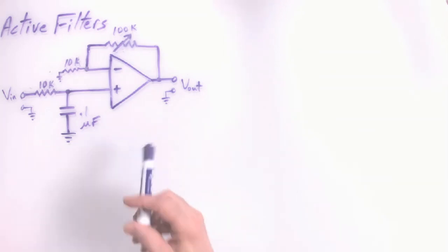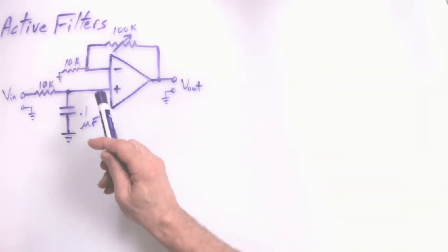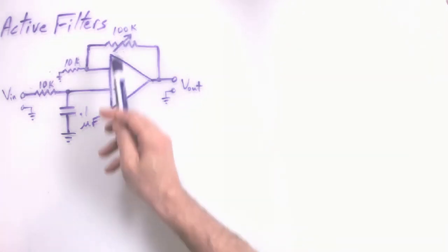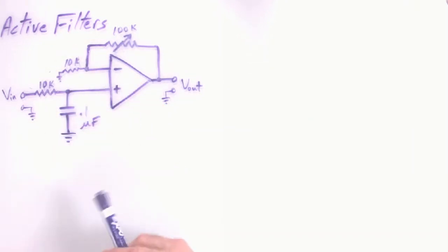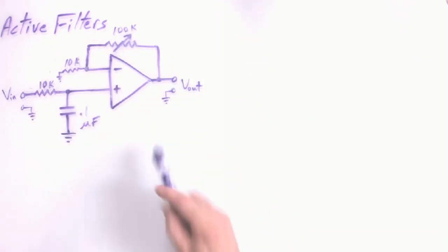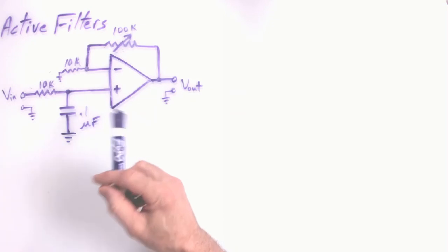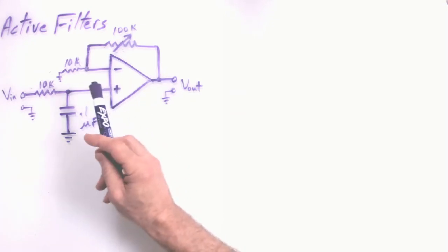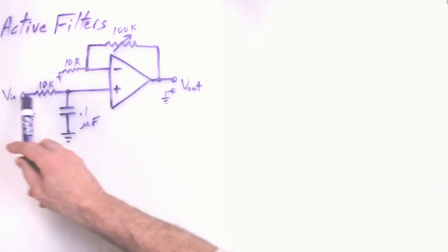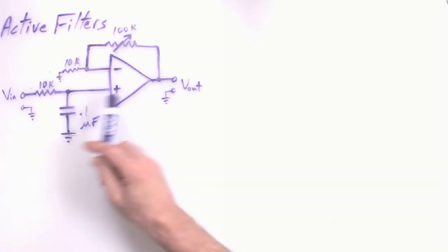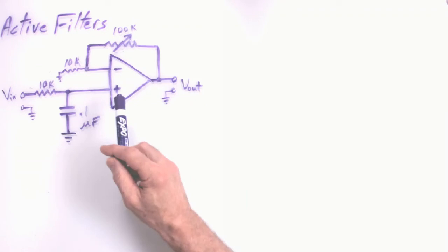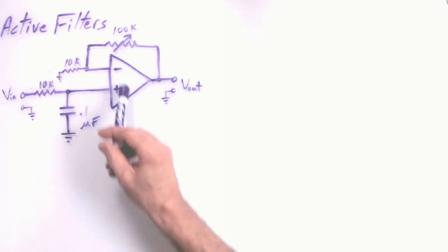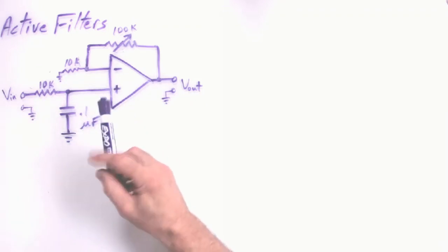And I just caught myself. I think I've been saying that we have a gain of 10 in our example. Has that been bugging you this whole time? So I'm losing points on a test there, right? My input is over here. It's coming in on my non-inverting input. Remember, we said try to use that as a memory aid, and so I have to add 1.